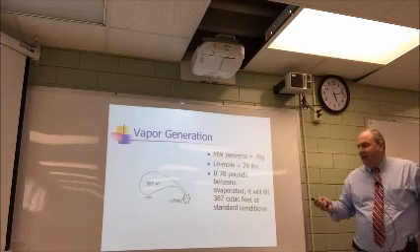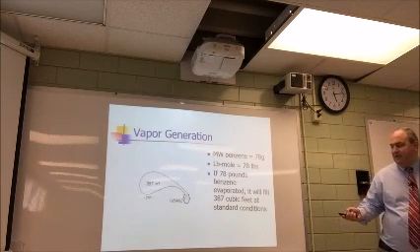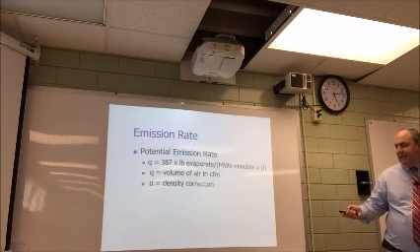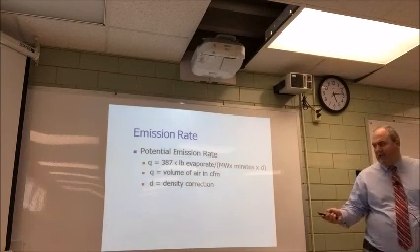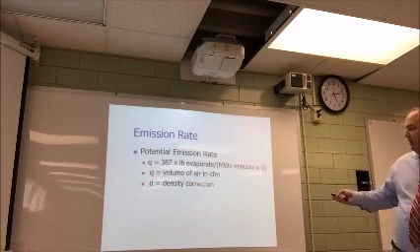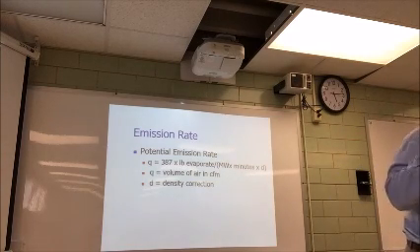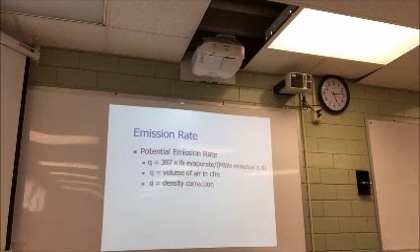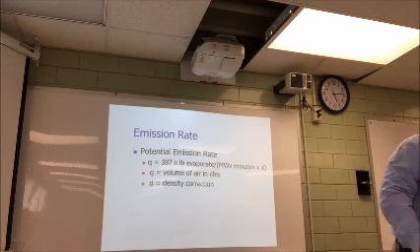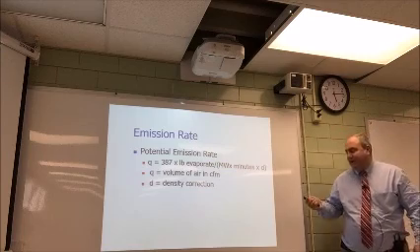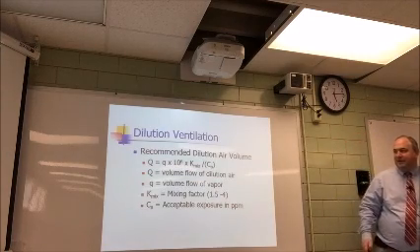So I want to go back. I want you guys to see what we're talking about. We've got 1 pound mole. We're putting it into the room. Again, what is the Q, or basically the volume of air in cubic feet per minute. Now the density will also play into it. If in a problem they don't give you the density, what do you get to do? Yeah, assume 1. Okay, don't get wrapped around the axles. If you're using a formula, it has a density in it, and you're trying to correct it. So there's your formula for emission rate.